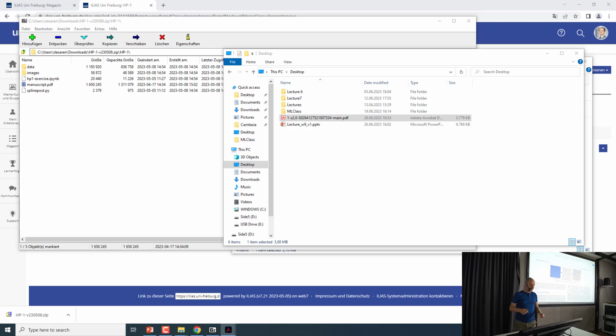Like here you have, I don't know, 1,000 or 100, sorry, points inside. And then according to specific rule, you sort of grow these grains, and then you smooth that and get this. It's Voronoi tessellation, one of the most powerful methods to generate any structures. So they generate 100,000 geometric patterns, and they test it in finite elements to get Young modulus and Poisson ratio.